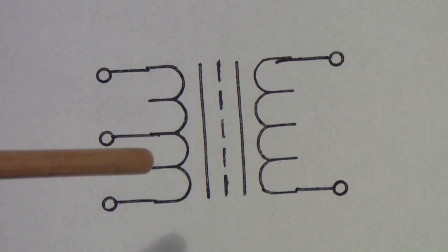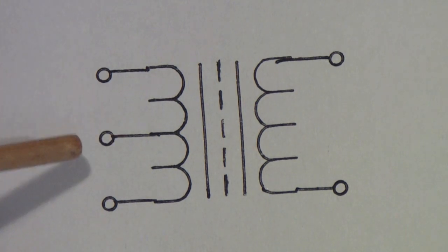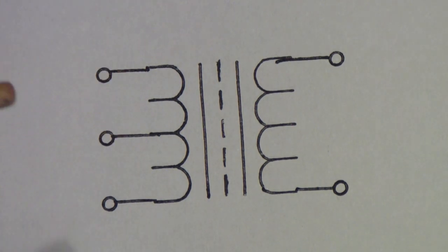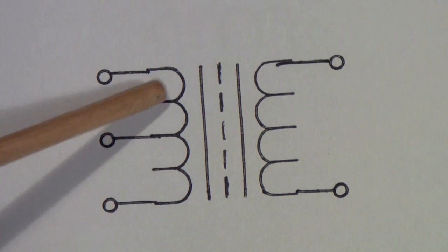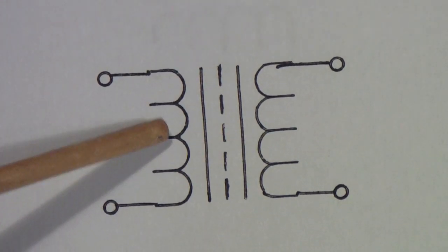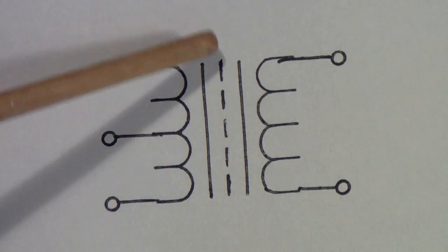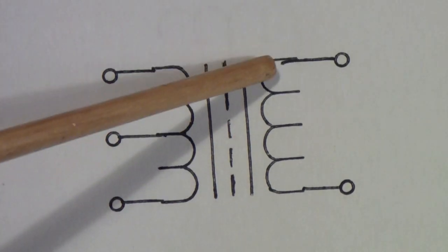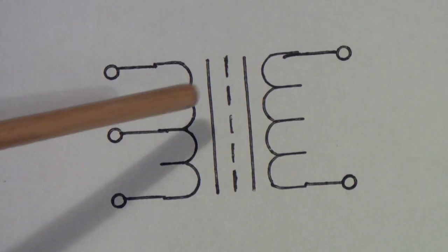But in the process, I'm also going to show you a characteristic you can measure with that same inductance meter that's called leakage inductance. And what leakage inductance is talking about is no transformer is perfectly efficient. Therefore, the current that you put in on one side produces a magnetizing effect in the core, which is transferred to the secondary, but not all of it gets transferred.